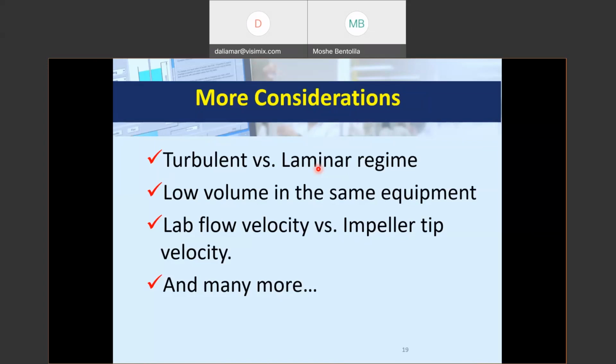So we are working with two different mechanisms of mass transfer, laminar layers versus eddies moving randomly, a completely different flow mechanism that will generate deviations in our results. So take care, and try to work in the same regime. This is one of the typical points.